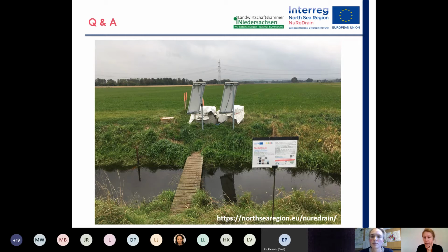Yeah, okay. Then more questions are popping up. Do you sieve the material to have a better hydraulic conductivity? Yes, the ICS material was sieved to remove this sludge particles between grains and to achieve a better hydraulic conductivity, because as you can see on the photo, the driving hydraulic force is very, very low.